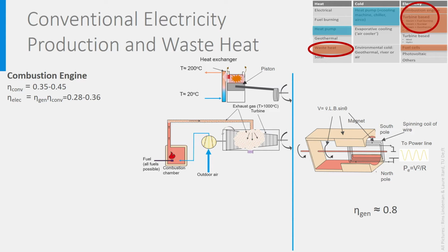Then the warm pressurized combustion exhaust gases are led to the turbine, where they expand, giving their energy to the turbine blades, which start rotating, driving at the right side the rotor of the generator and at the left side the rotor of the compressor. So, this compressor needs no electricity as it is powered by the turbine itself.